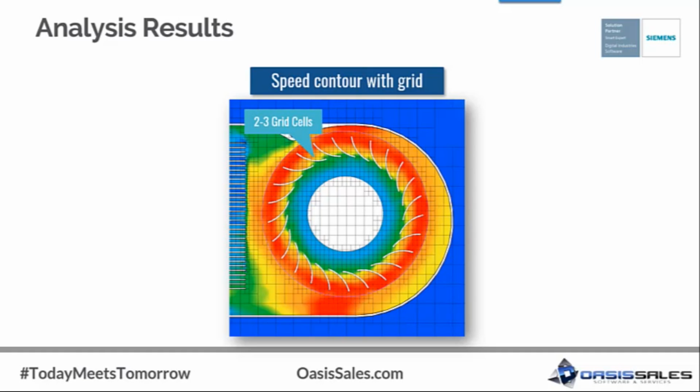Though the grid is coarse, I would like you to notice how well the geometry is resolved, particularly the blades, with the smart cell technique used by FloTHERM XT. Even the curvature of the graphics card cover is captured well with no additional grid settings or higher mesh count. This model has about 580,000 grid cells.